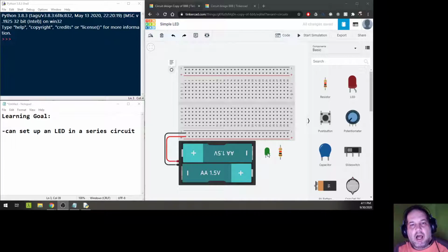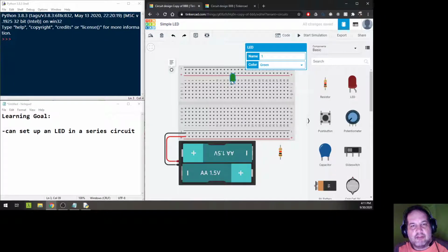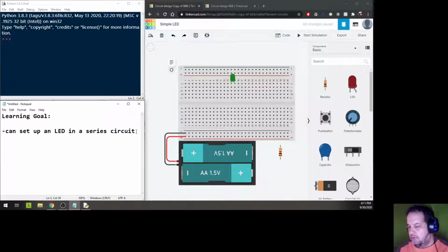Okay. We're going to assume in this class that our LEDs are rated for 20 milliamps. Okay, so let's put that down. Assume rated for 20 milliamps. But then we immediately need to note that this is the same as 0.02 amps, because we're going to have to use this with Ohm's law to actually calculate our resistance that we're going to use.